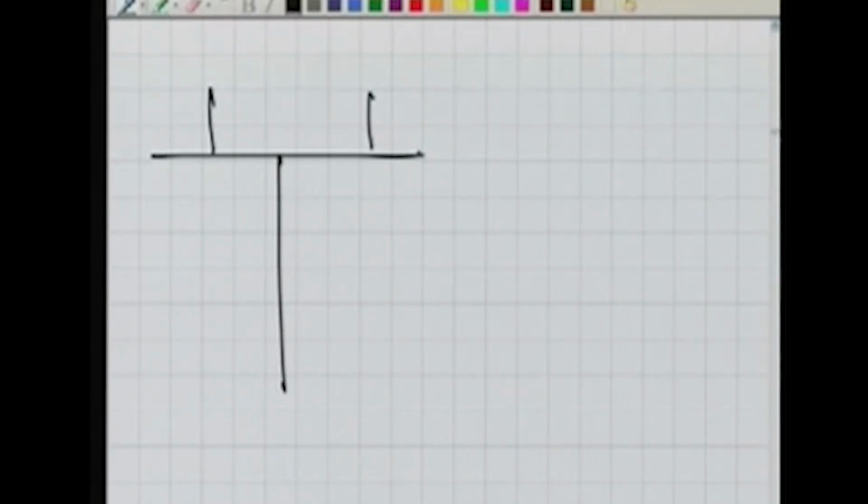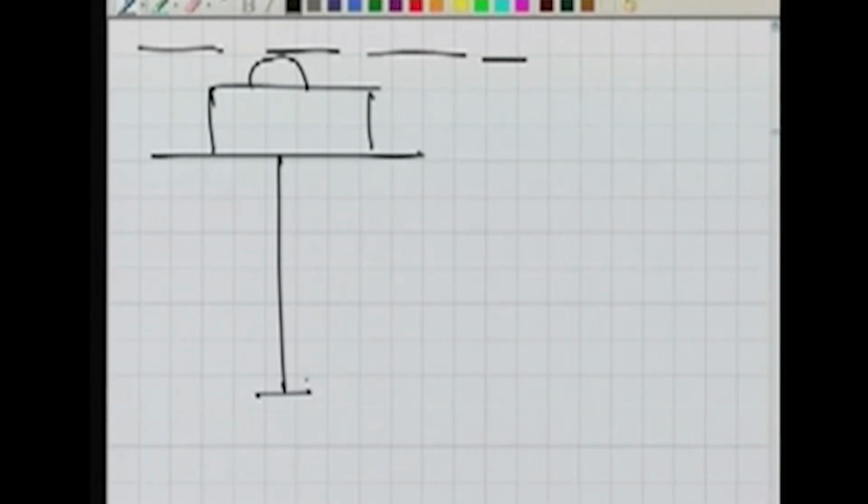B and A, and this is how the bubble will become now. Because by using the foot screw, we have changed this vertical axis from this position to this position, eliminated this error of E. So our final stage will look like this. So we can eliminate this error from the instrument. We have seen the test of this, we have seen how to eliminate this. So this is a kind of permanent adjustment of the instrument.